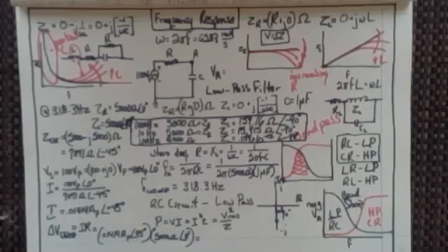So what we see, once we multiply these two things together, is we get 70.71 volts at an angle, let's add them, 45 plus 0 gives me 45 degrees, doesn't it? So 70.71 volts at 45 degrees.